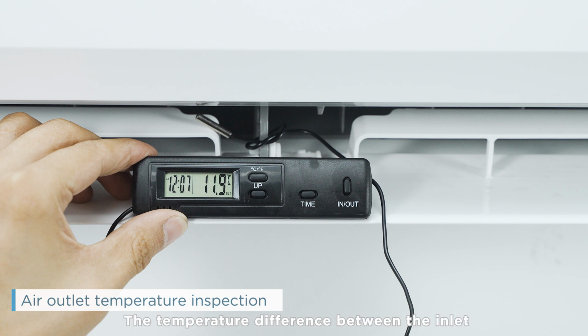The temperature difference between the inlet and outlet of the indoor unit during cooling mode should be above 8 degrees Celsius. In heating mode, the temperature difference between the inlet and outlet air should be above 12 degrees Celsius.